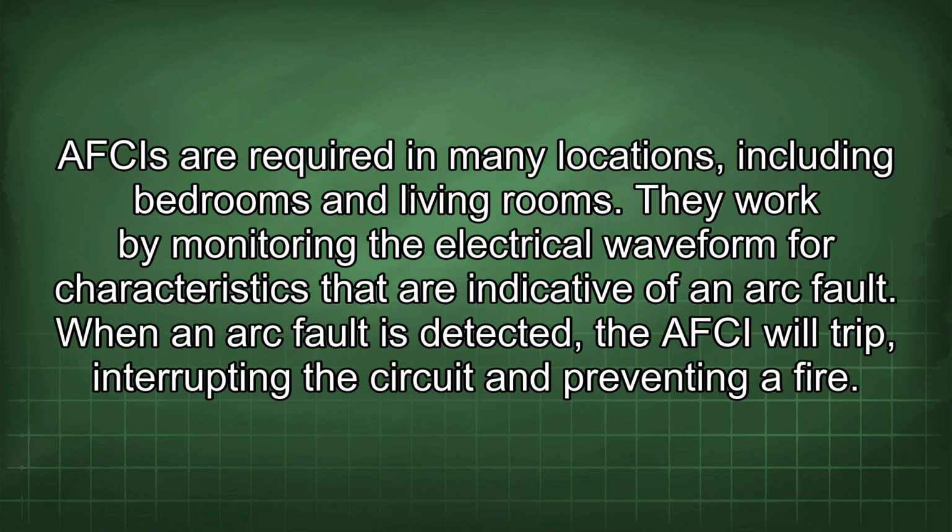AFCIs are required in many locations, including bedrooms and living rooms. They work by monitoring the electrical waveform for characteristics that are indicative of an arc fault. When an arc fault is detected, the AFCI will trip, interrupting the circuit and preventing a fire.